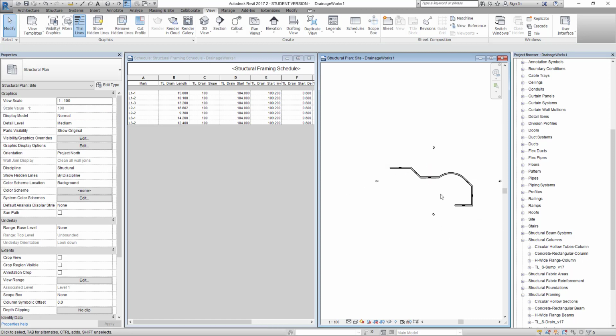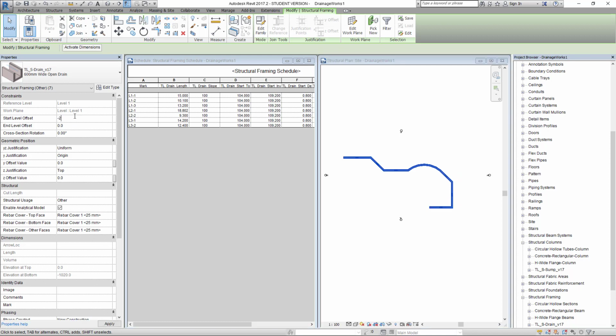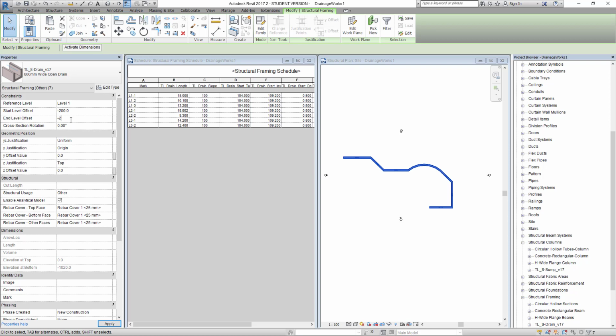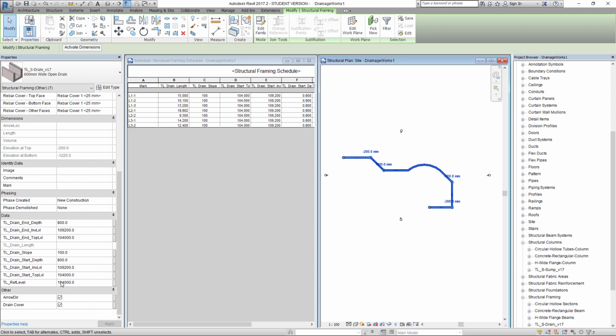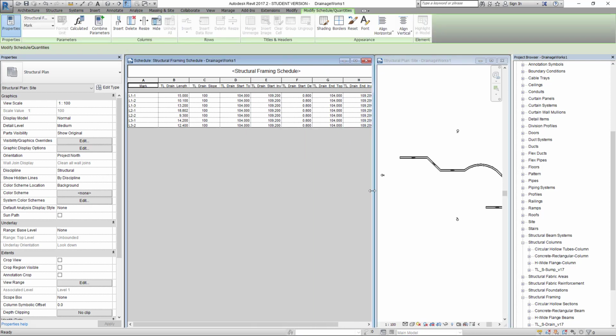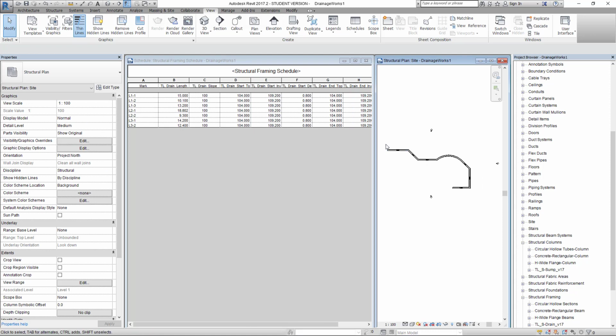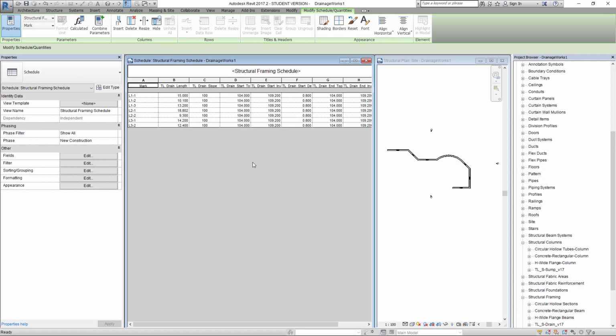If our drain tops, for example, all of our drain tops are not at 0, maybe they have minus 200 for example. If minus 200, then normally what we need to do is come here and subtract 200 from the reference level, and we will get the start and end top level value, right? So if we use this code, then this code will easily update according to that change. So now all drains are offset minus 200 from the reference level. So we don't need to calculate and type it one by one. What we need to do is run the code.